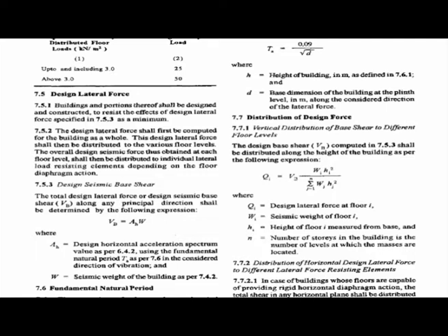If I can calculate earthquake load, then I can analyze the structures due to dead load, live load, and then lateral load. On the basis of that we can compute the bending moment and shear force in each member.